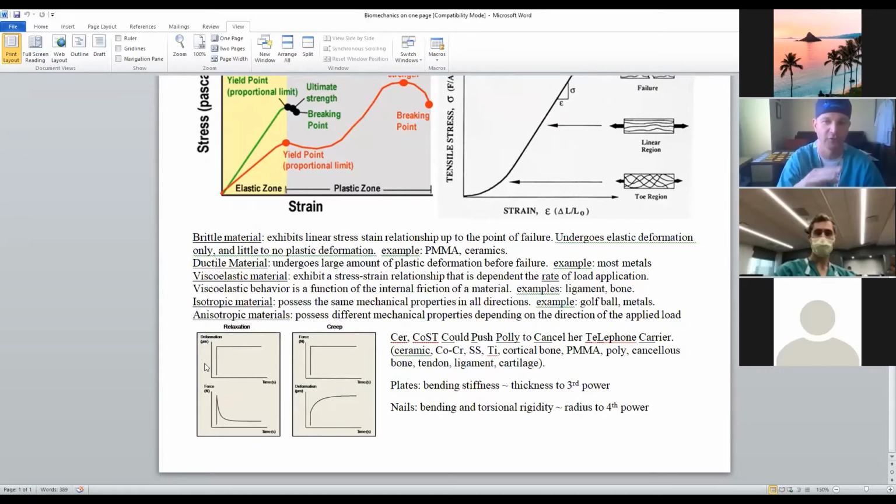That force over time relaxes, and that's what they call stress relaxation. So you pull it 1 inch, and then you measure the amount of force that it takes between your fingers to hold it there over time, and it's probably pretty quick, on the order of seconds. That amount of stress to hold it there decays over time. So that's what they mean by stress relaxation.